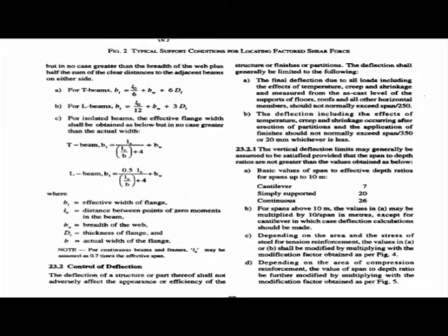Let us consider this one here, say 15 meter span. First you get depth equal to 15 by 20, and then modify with 10 by 15.